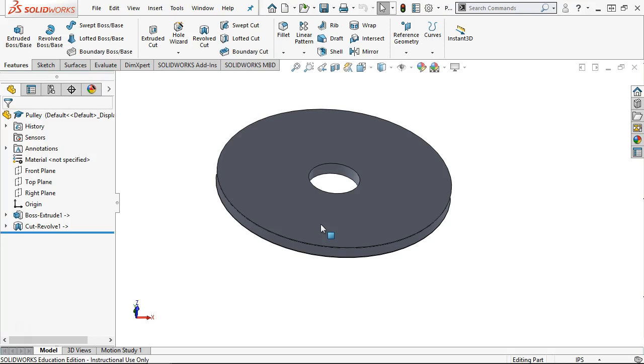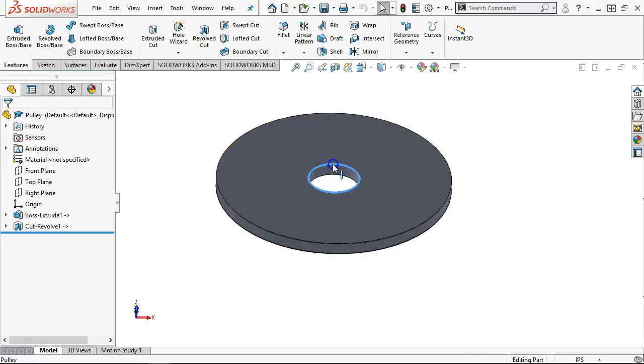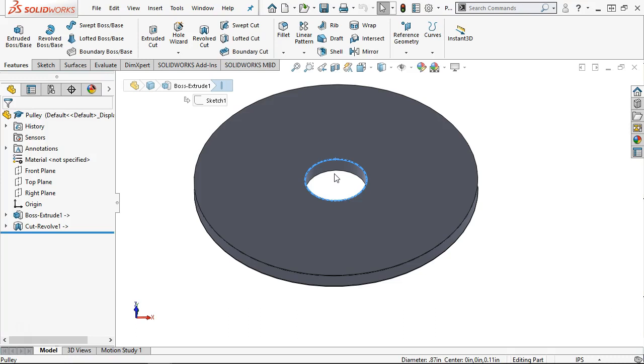That freaks me out already. So as we go through the numbers, they're very small differences. Depending on how this tolerance and what the bearings come in at end up interacting, we have that allowance for the force fit. If both of those end up at their maximum material condition, the largest bearing size and the smallest hole size, then I could have a medium fit of about 2 thousandths between these.